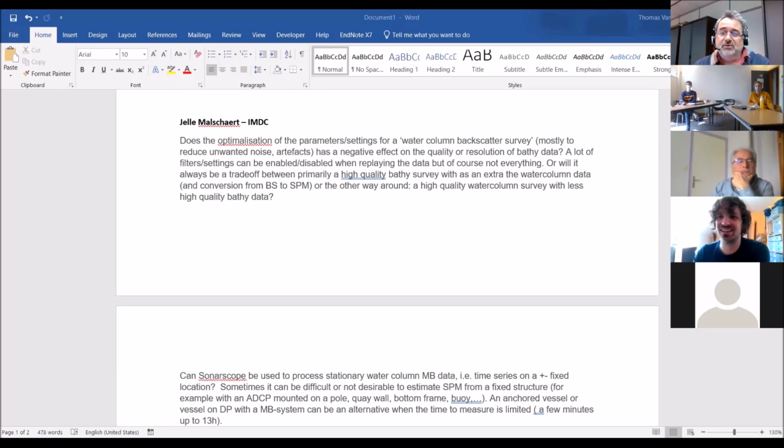And again, what we are doing is using a tool that is mainly produced for hydrographic purposes to investigate the water column. But I'm not sure you need to find a compromise to use that tool. And again, think about the pulse length. We use a medium pulse length because there is no solution about that. If you change the pulse length, that changes your amplitude dramatically. And probably medium pulse length is not the best pulse length for hydrographic purposes.